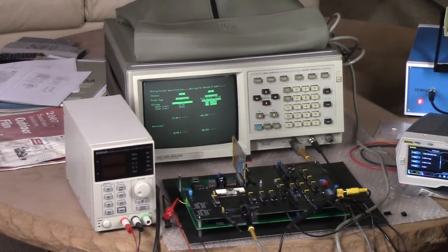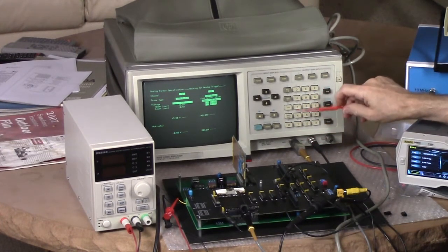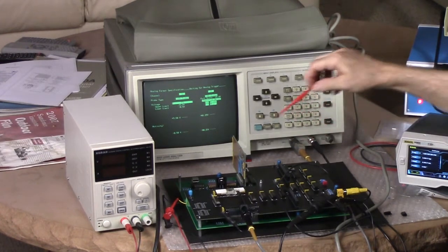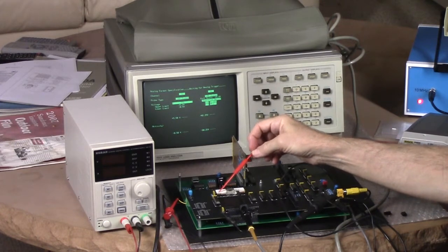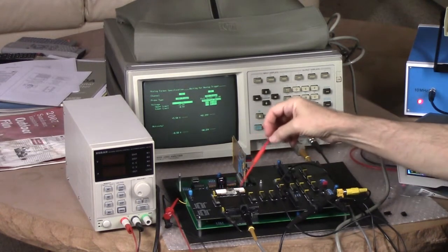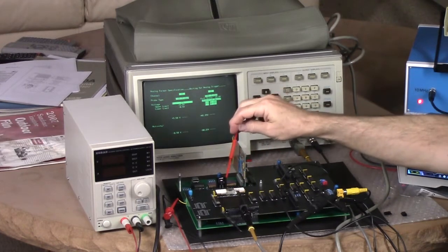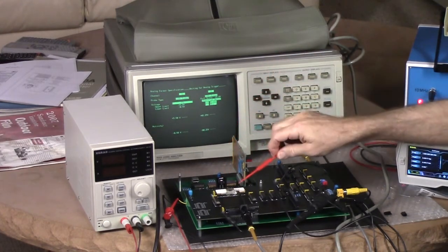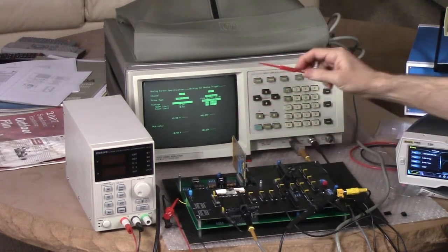Here it is. I have 2 channels here. What I'm looking at on channel 1 is the vertical sync output from the processor chip. When I say processor here, I mean the graphics processor, not the central processor. That's a positive going pulse.